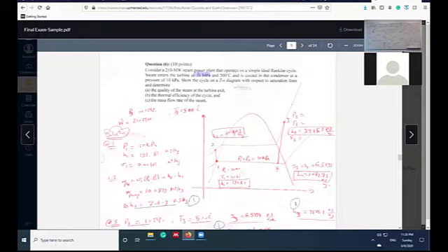This is water. The condenser exit pressure 10 kilopascal. So the P1 and P4 are 10 kilopascal because they are always constant pressure lines. This is constant pressure line, the same as what you see in the board. Pressure 1 equal P4, pressure 2 equal P3.